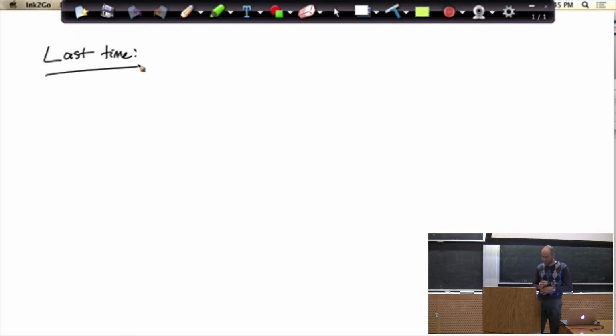Last time I was here, we talked about starting to apply the ideas of dynamic programming to the Acrobot and Cartpole. We said you could discretize the whole space and do the discretized value iteration that we know is going to work and we can rely on. There's no worries about whether it converges or not. It's guaranteed to work, but we would have to sacrifice either a lot of computation time or a pretty sparse discretization of the space.